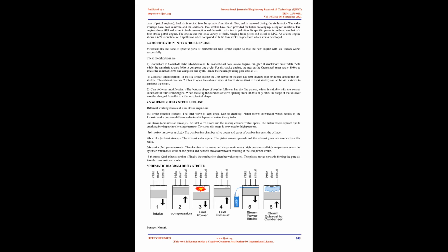The principle of the method is to replace an entire continuous domain by a number of subdomains in which the unknown function is represented by simple interpolation functions with unknown coefficients. Discretization or subdivision of the domain. Selection of the interpolation functions, to provide an approximation of the unknown solution within an element. Formulation of the system of equations, also the major step in FEM.